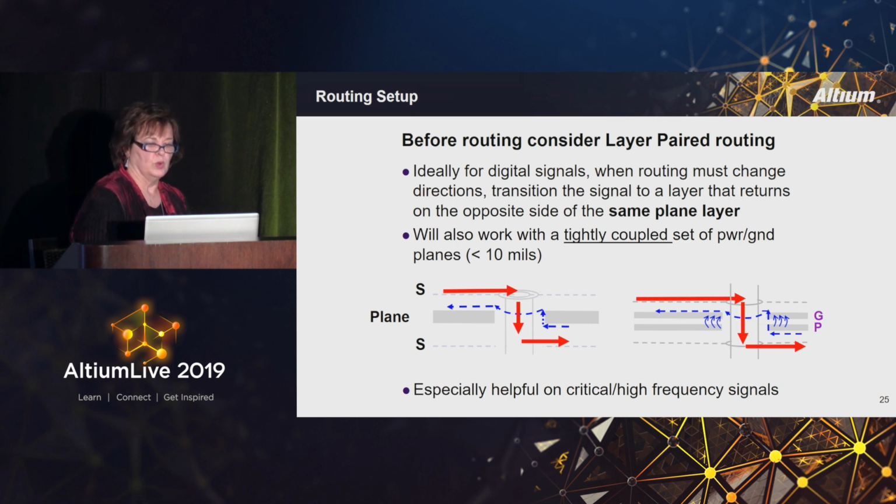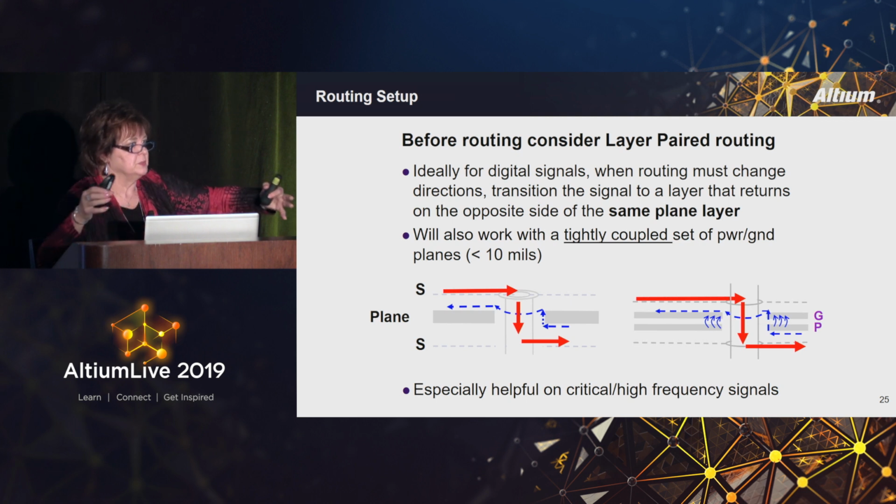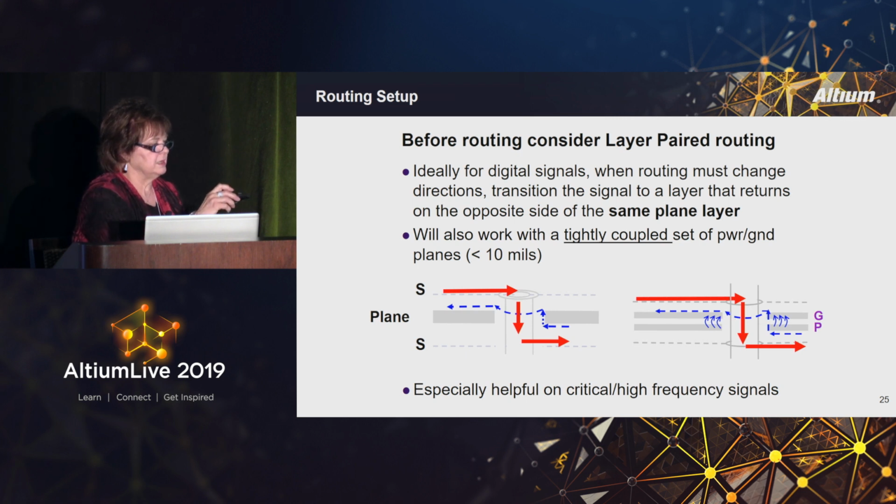It simply won't work. And if you separate these planes, you get lots of common mode energy that spreads out in that area. If you think about this as layer 1 and this is 2, and if these were much, much farther apart, so this would be 3 and 4, and you have a 4-layer board, think about how much energy now there is that's spreading out in that area.